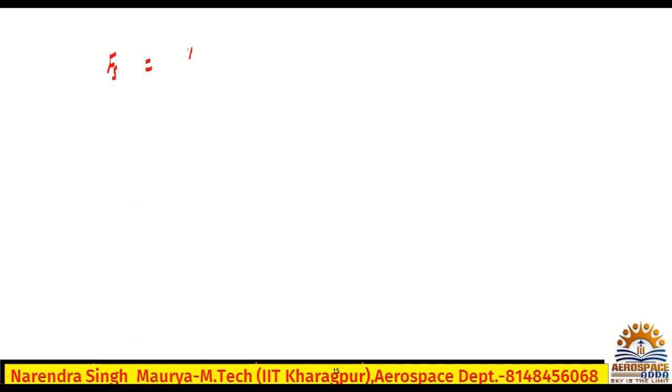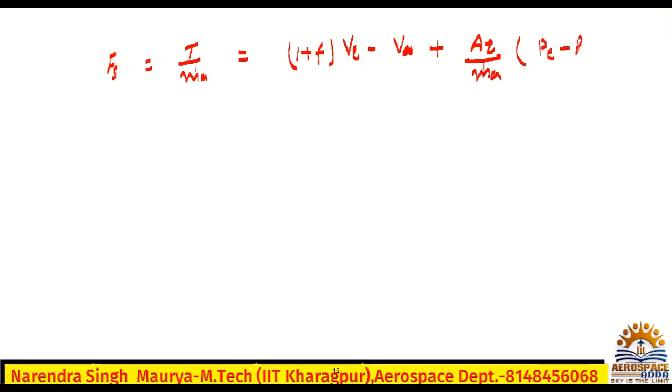Fs, thrust divided by mass flow rate of the air, is equal to (1 plus f) times (Ve minus V infinity), plus Ae divided by mass flow rate of the air, in bracket (Pe minus P infinity).